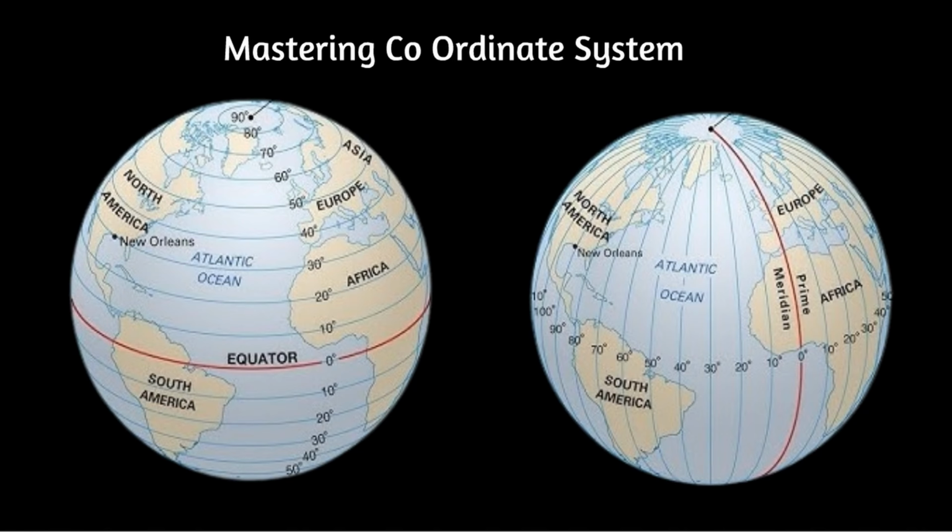Northing, that is the y coordinate, is used to measure distance north or south from a reference point. It may be from the equator or generally from a baseline used for every project. These values are typically measured in meters and are part of the Universal Transverse Mercator or State Plane Coordinate System.